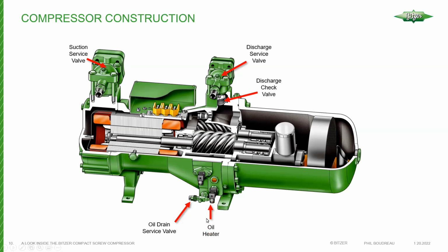Very important that the oil heater is energized several hours, probably 12 hours or so, or a good day prior to starting up a compressor. And this is the case with semi-hermetic. This is the case with all compressors, in my opinion, particularly when you're running HFC refrigerants and HFOs, which we don't see much of here yet in North America because the codes and standards do not permit that quite yet. But it's very important because the heater limits the amount of refrigerant that's going to be in the oil. More refrigerant in the oil means less viscosity, means less lubrication, and reduced compressor life. So energize those heaters and give them enough time to start up.